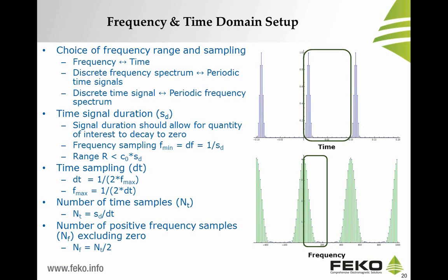And important also for the time signal is you need to consider a range based on the time duration and the speed of the medium in which the traveling occurs. In other words, we selected the near fields to be calculated at 3 meters away from the car because 3 meters is well less than the speed of light in this case times the duration set for the signals, as you will see just now.